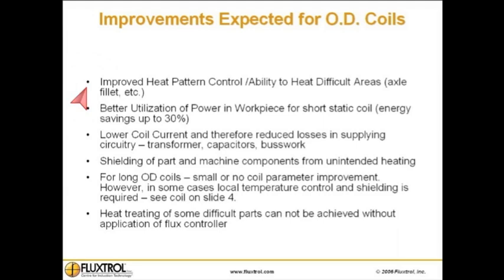Improvements expected for OD coils. Improved heat pattern control and/or ability to heat difficult areas, axle fillet, etc. Better utilization of power in workpiece for short static coil, energy savings up to 30%. Lower coil current and therefore reduced losses in supplying circuitry, transformer, capacitors, buswork. Shielding of part and machine components from unintended heating.